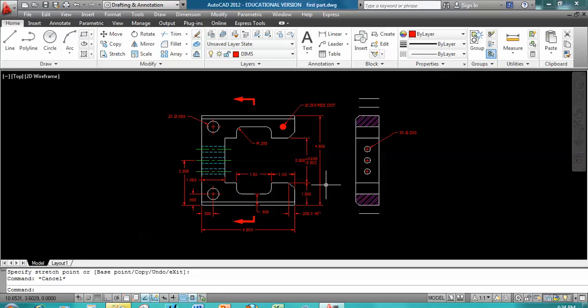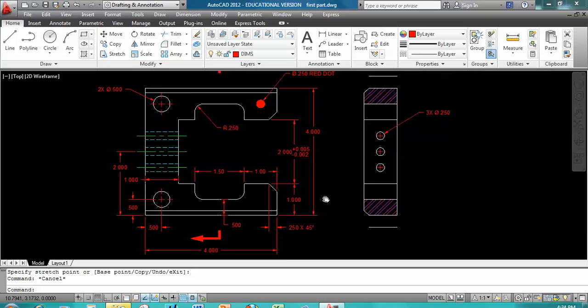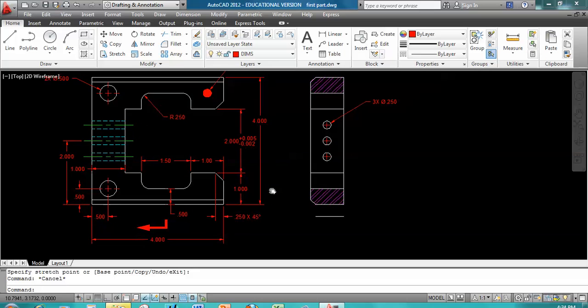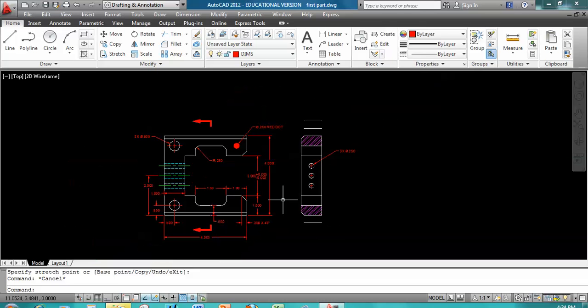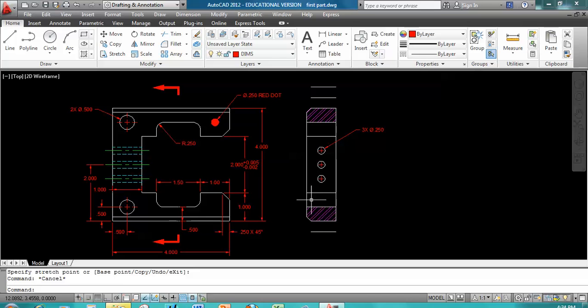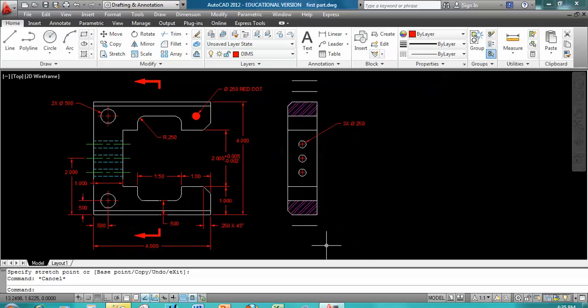to look for dimensions. Dimensions should not be placed on top of each other, should not overlap the drawing. Dimensions should possibly be kept off of the drawing, and the drawing should be dimensioned uniformly. So here we have a few more and then we'll be done.